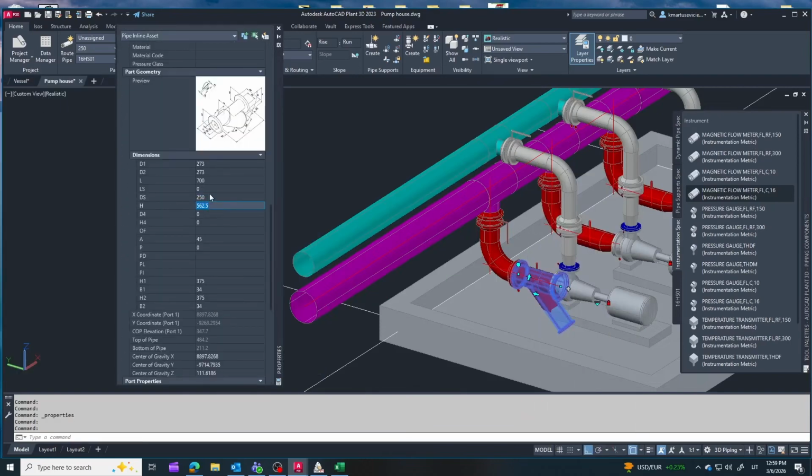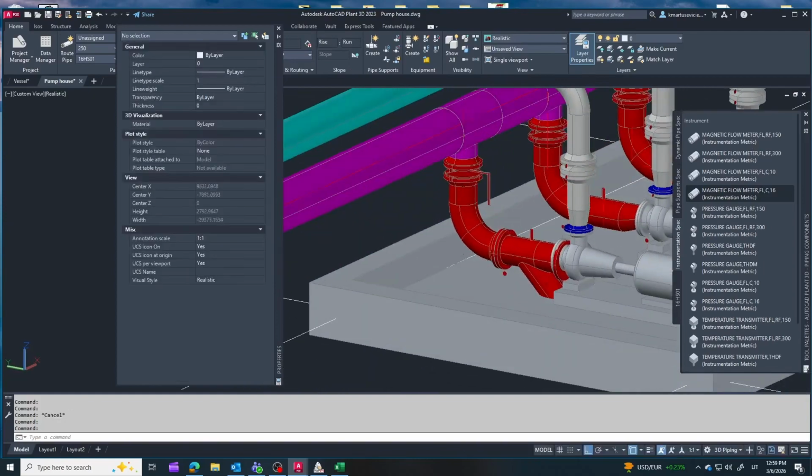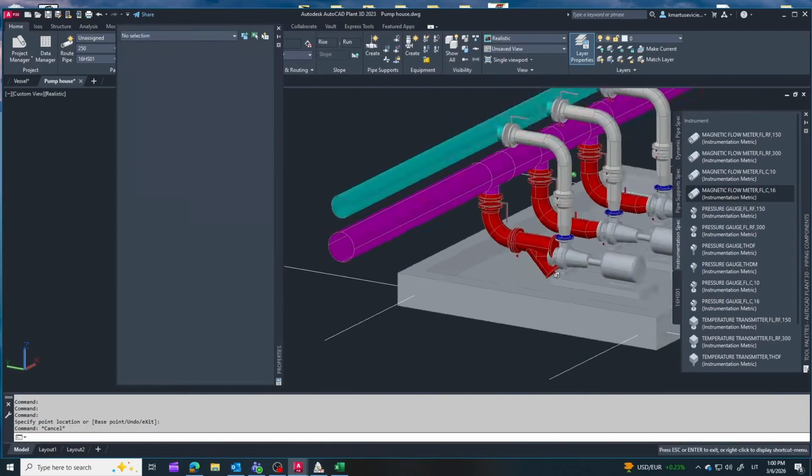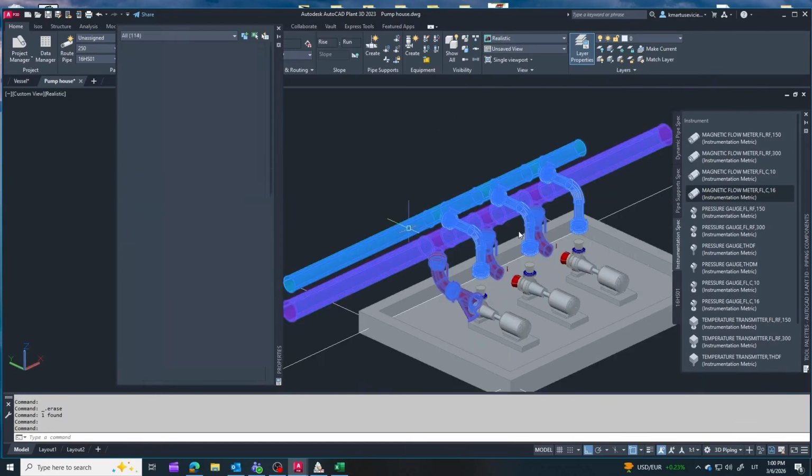These large diameter strainers do not fit inside our pump house, so I need to adjust the size of the concrete pit. It is always easier to fix these issues on the drawing rather than later on the construction site. To solve this, we will raise the manifolds and extend the concrete pit.